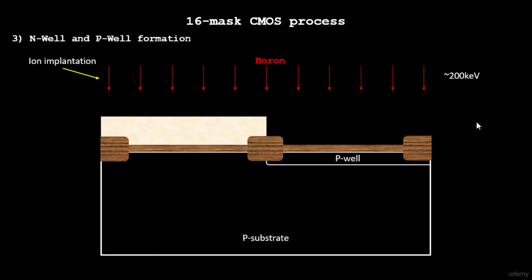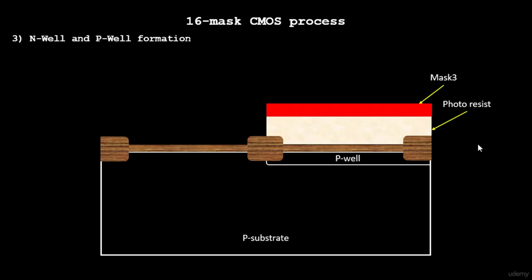A furnace is a place which works at very high temperature, up to 900 to 1000 degrees Celsius, and that actually helps to grow the oxide in the other areas. So we have grown the first level of silicon dioxide in an oxidation furnace. Now there is a second level of oxidation growth, so we'll do that now, and it will look something like this.